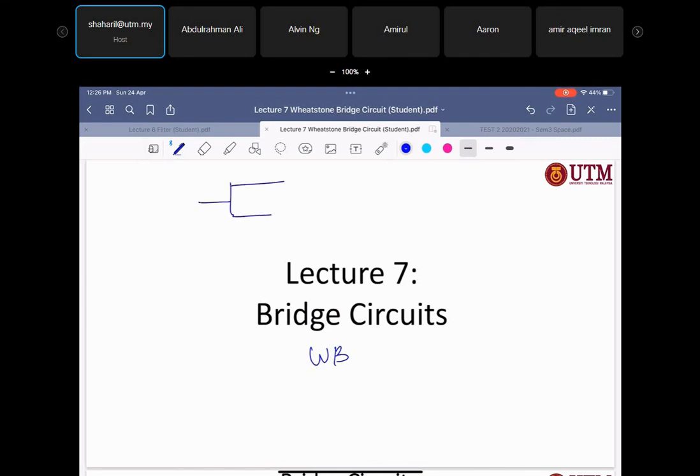So when we have our transducer here, and then we have the signal conditioning here. So what it does is, for example, our temperature transducer detects temperature, it will produce in terms of ohm, right? This can be like the RTD or thermistor. Yep, it can produce in terms of ohm. And then when using the Wheatstone bridge, it can convert it into another parameter. It can convert it into millivolt. Okay, so this is what you use, what we call the Wheatstone bridge.